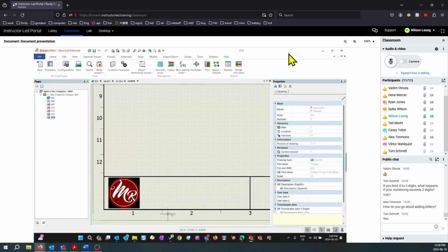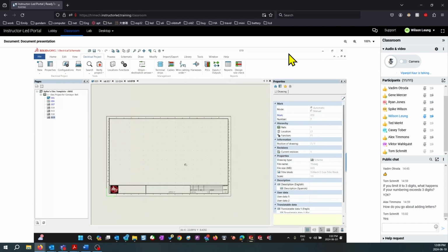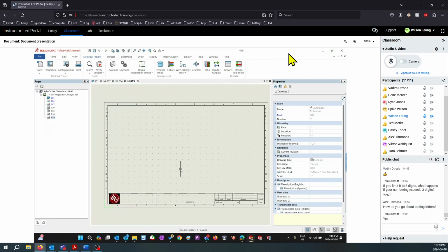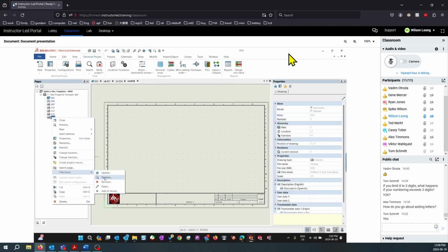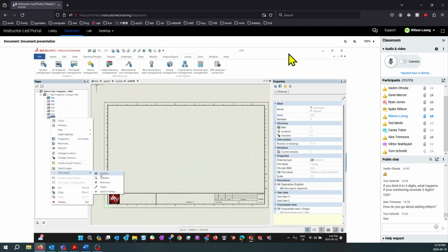So whatever company's logo I had used, I was working with one of our clients, and you could see that title block now started appearing for me here. So I could right click, title block, replace title block. Remove title block is not required when replace works for you. If you open title block, open the DWG file, make changes, you can save your work. Now you have to right click title block, update title block. If Ryan tells me, VIP, your logo doesn't look great, reposition it.